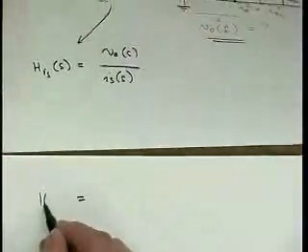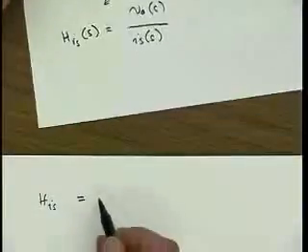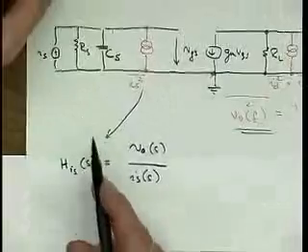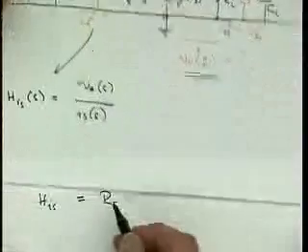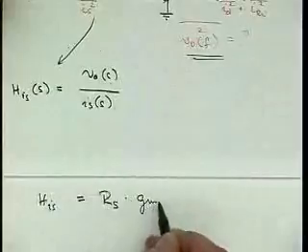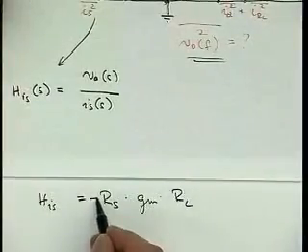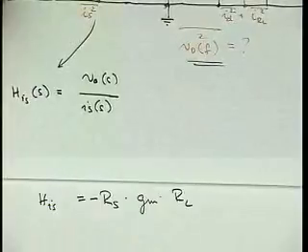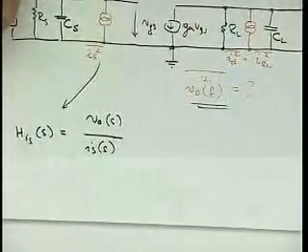So this HIS: first we turn IS here into a voltage, and the proportionality constant for that is RS. Then we amplify it by GM times RL, and if you want to be precise, there is also a minus sign, although here we ultimately get rid of it.